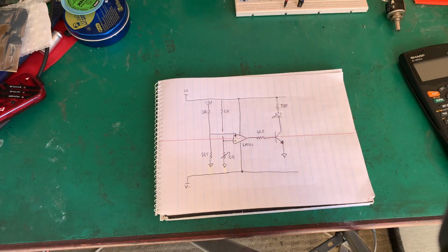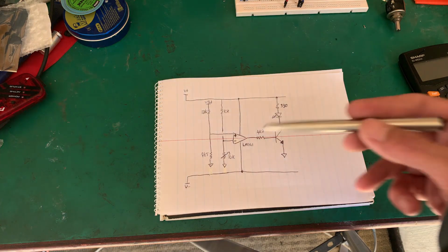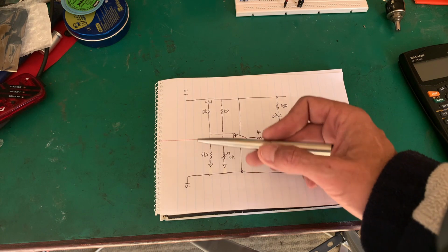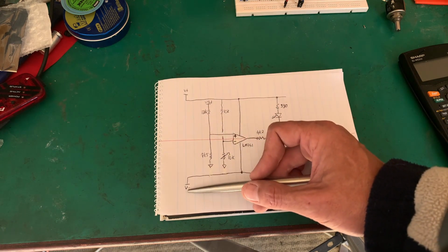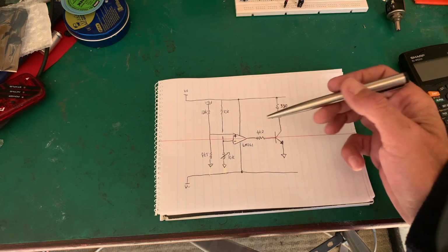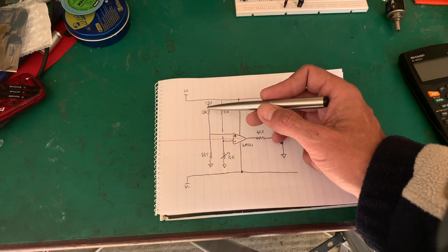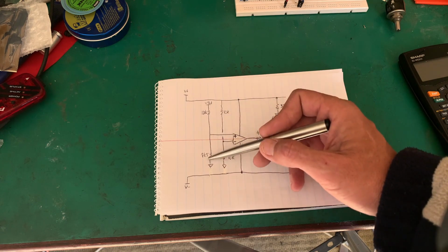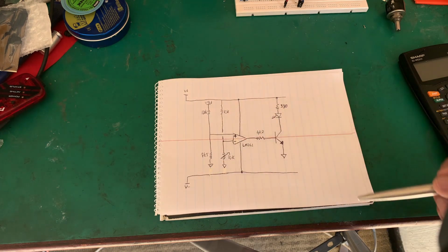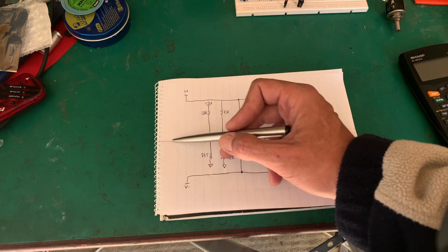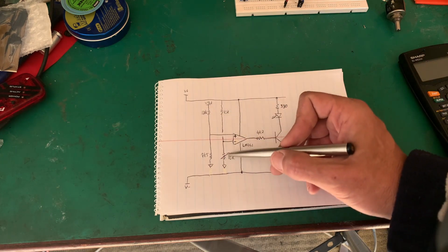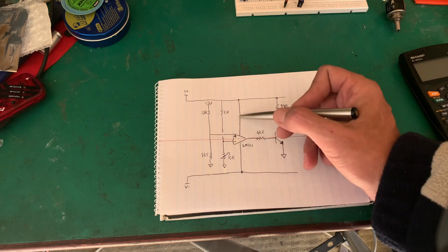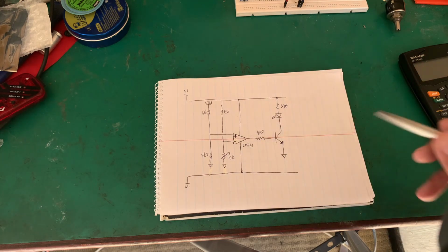Right, we have another complex looking circuit, and it's really not. We're building on the previous circuit. Notice I have my V plus feeding the op-amp. I have my V minus feeding the op-amp from the previous circuit. But now I have this funny thing, VBAT, through this resistor ratio to the virtual ground, to that middle point of that other one. We also have another thing here, 10K, a pot to the virtual ground, and these are going to our two signals.